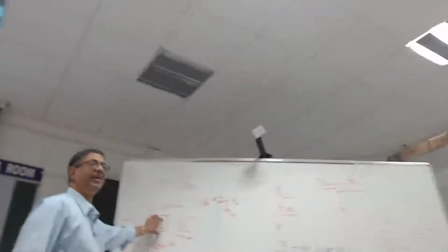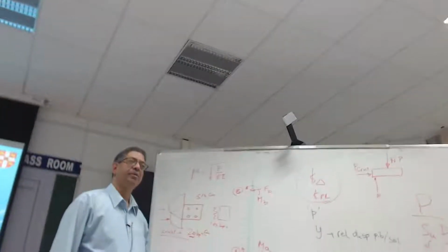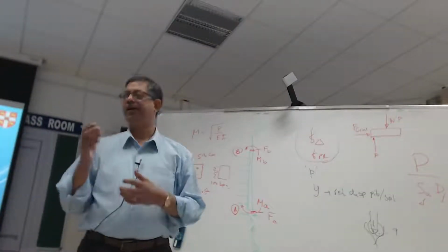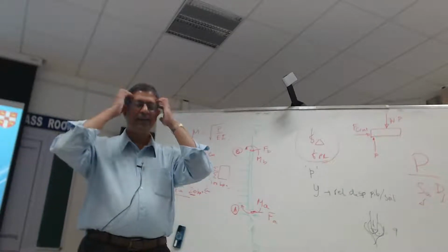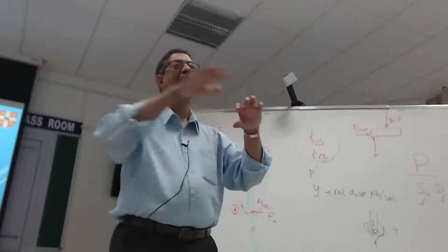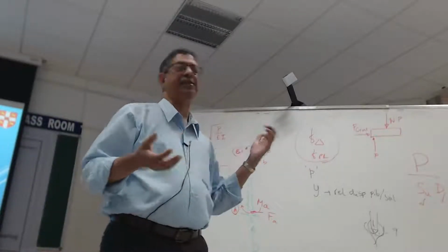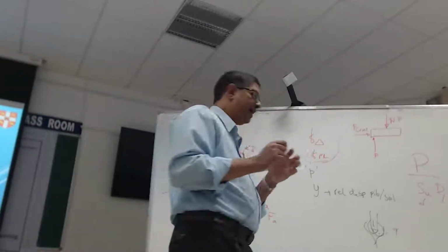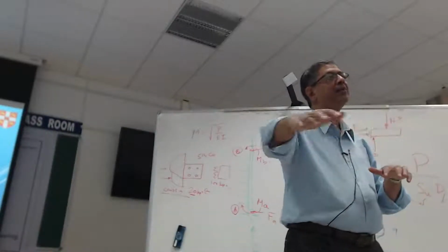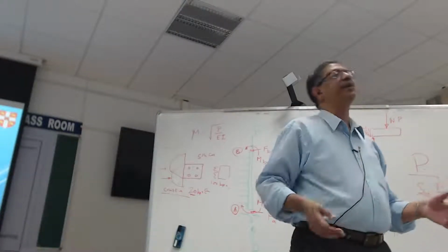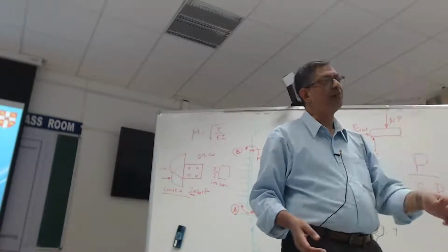It's actually this thing that dominates the show. The critical situation is if you have a clay layer on the top, you'd expect this as a problem. But where you need to be careful from a design point of view is when you've got just a sand bed sloping down, and you think it's all going to liquefy. But at the time of the earthquake, the water table is 5 meters below.